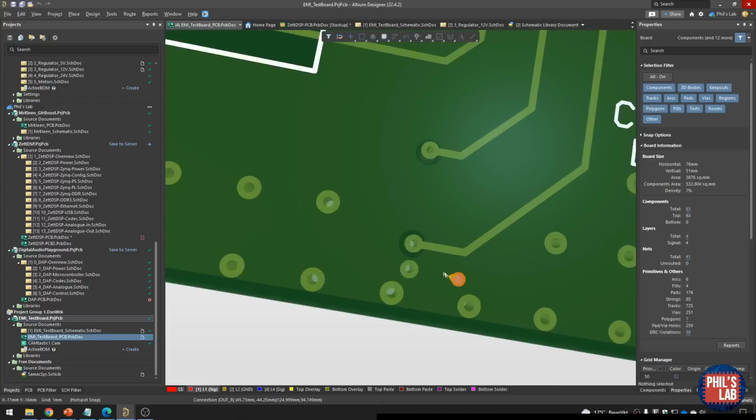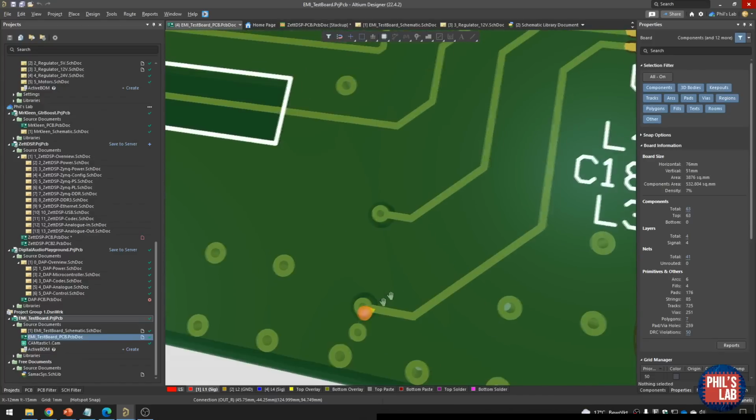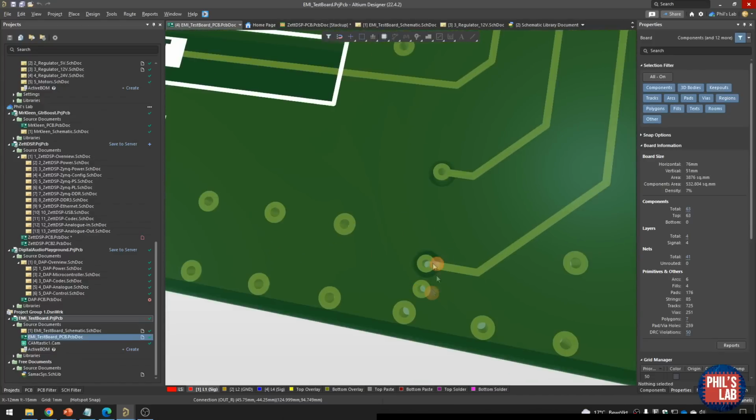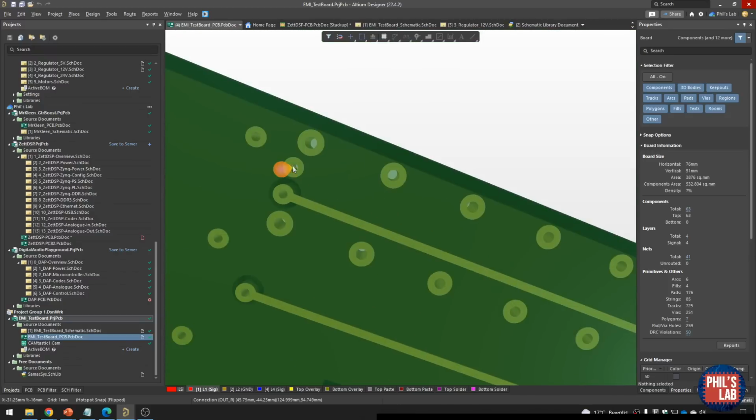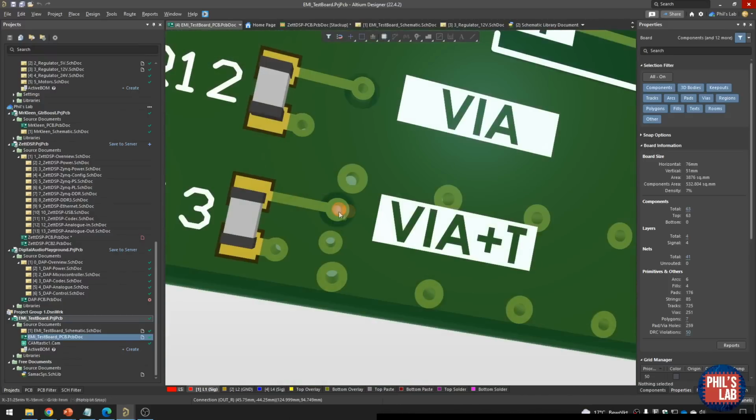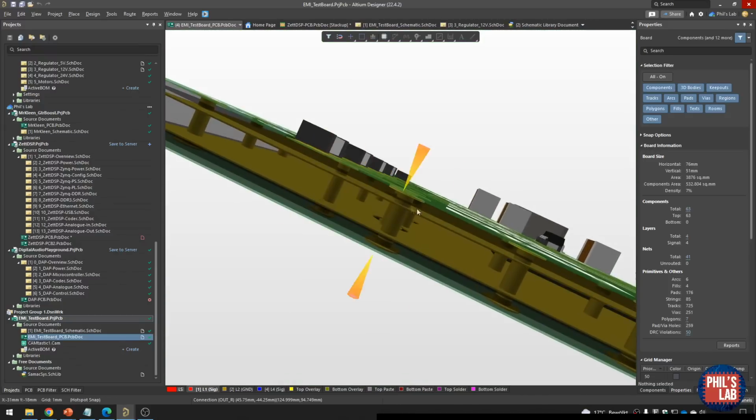The better case to do it is have your signal trace burying down, then a ground via very close to the signal via. The signal carries on the bottom side of the PCB and up again with a ground via adjacent to it. And this improves the coupling for this 4-layer board when I'm transitioning from the top to the bottom layer and switching reference planes.